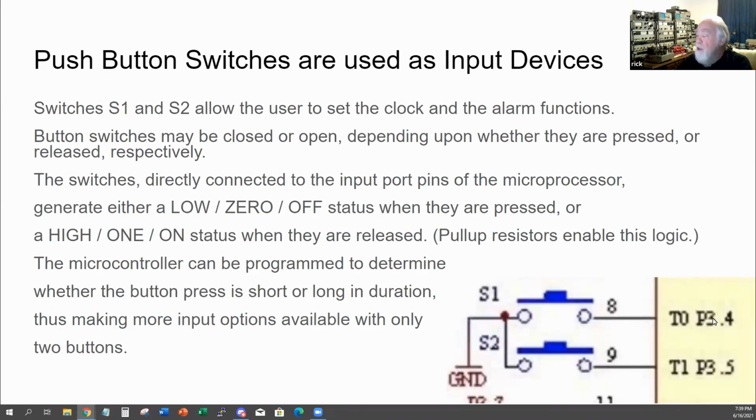So the push buttons are simply connected to an I/O port. Ground is the 0 or the negative battery return. And inside the computer program, you would actually define what's called a pull-up resistor. It's a logical resistor that you can define inside the computer processor that actually causes this pin to be raised to a positive voltage, which is a 1 in boolean or digital logic.